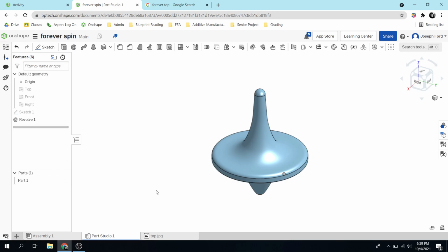What the slicer program does is slice up all of those triangles into layers. And then G-code can be created because each layer has a geometry, and the tool that the G-code is programmed for would just follow each slice.